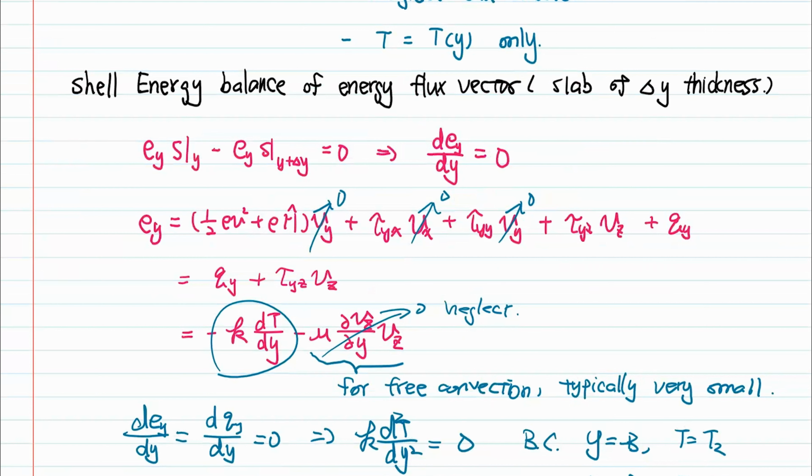The work associated with shear here is not going to be very significant. With that said, we can assume that the temperature profile is not affected by the velocity profile. Obviously, if you're having a very violent boiling, then you cannot make this simple assumption. But in our present case, the temperature difference is small enough that you don't have that happening.